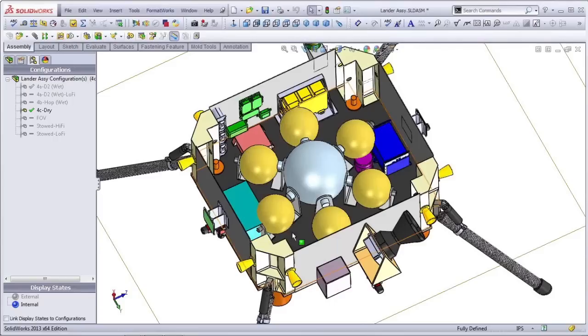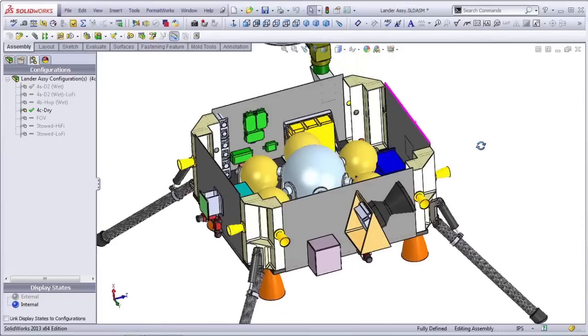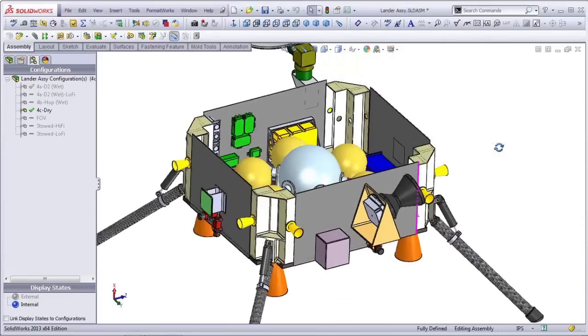So that gives you a little bit of a feel for how to do mass properties. Now, each one of these components in here has a mass applied, or it has a density that represents the center of mass. So it's a very bottoms-up, data entry consistent system, but once you have it all set up and in place, all this information can be reused.